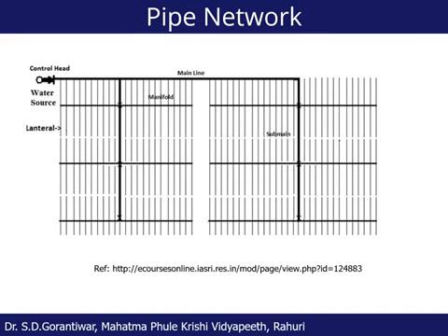So this is quite a huge field. You see there is a main line, then there is a sub main line, then there is a manifold, and then there are laterals. So this is a big field, and all kinds of nomenclatured pipes exist in this field. The purpose of the main pipeline is to bring water from the water source up to the field, and that is what it is doing in this figure.